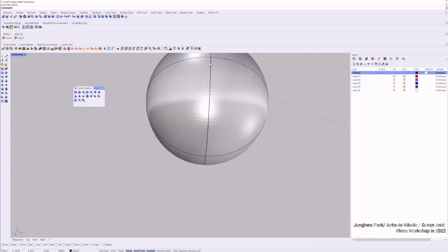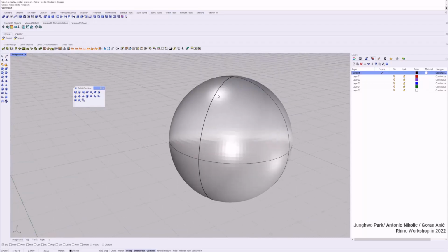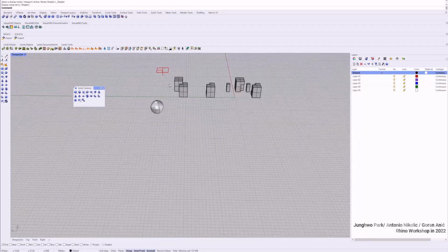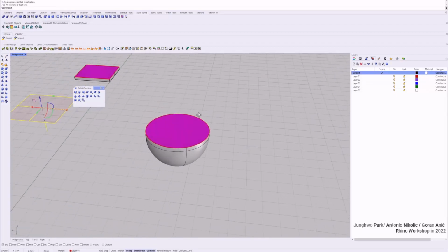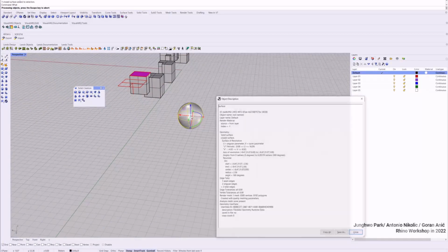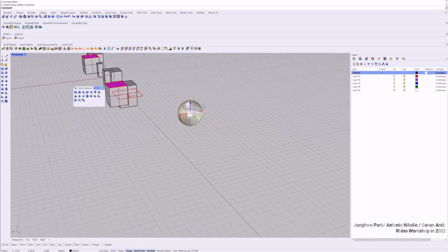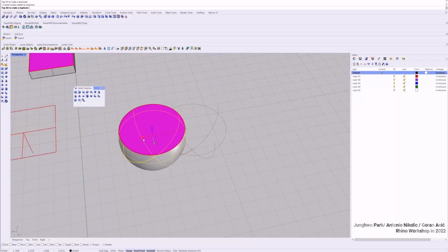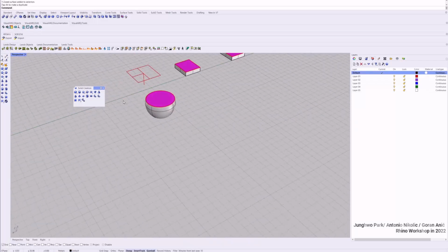You can see here one division line, and it's just revolved as one surface, but Rhino recognizes it as a solid. So if I move my clipping plane, as you can see, this is solid. But if I explode, the result will still be a surface, because it's a single surface. It keeps being a sphere forever. Okay.